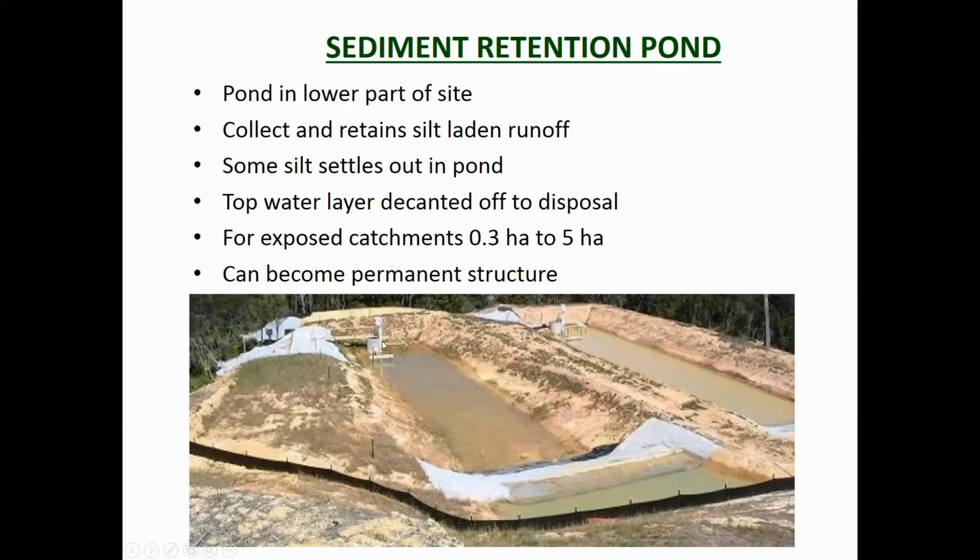And you can see at the end there's the outlet structure, and we're not really looking at it. You need to look at GDO5 for that, but you can see that there's a T there. And so what that is, there's an outlet there, and that floats on the surface. So you can see that's just floating on the surface there. So it's two pipes. The top pipe is sealed and is afloat, and the bottom pipe is the outlet.